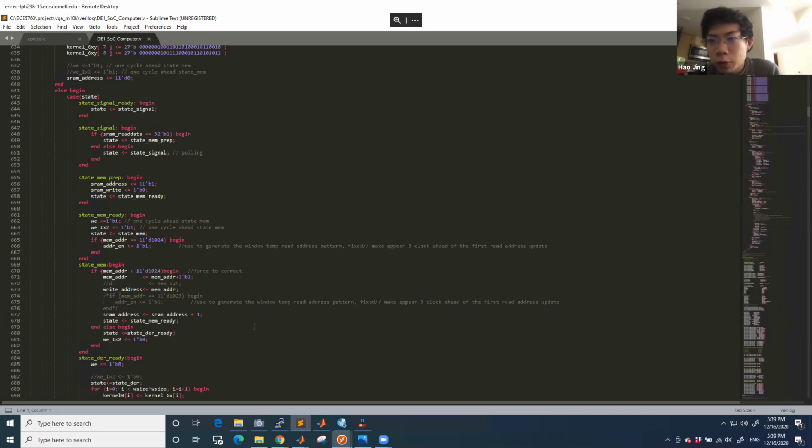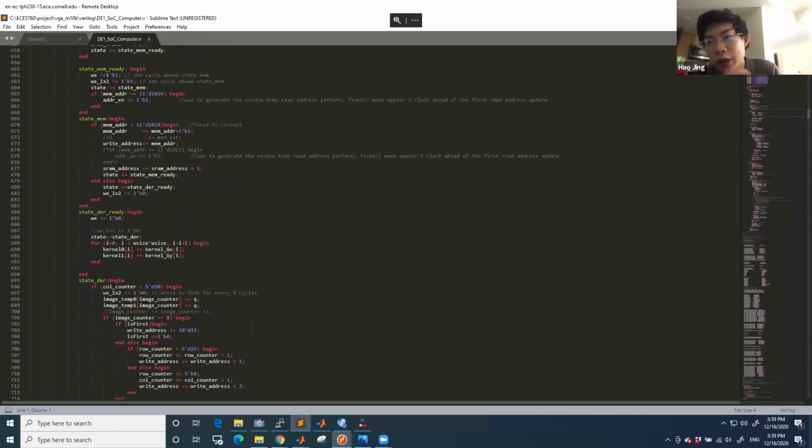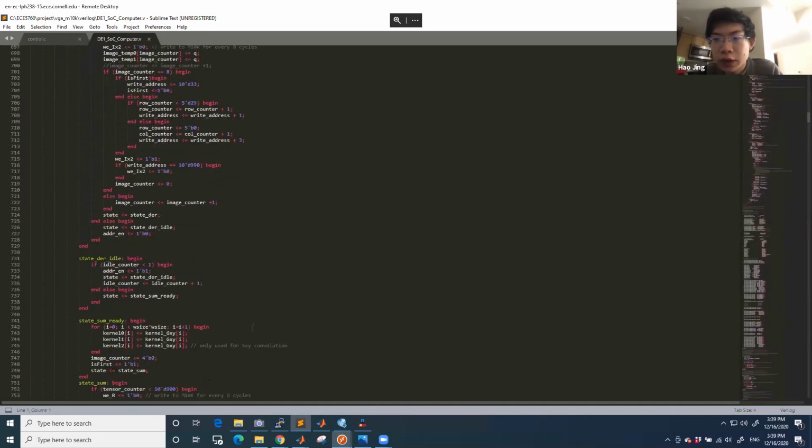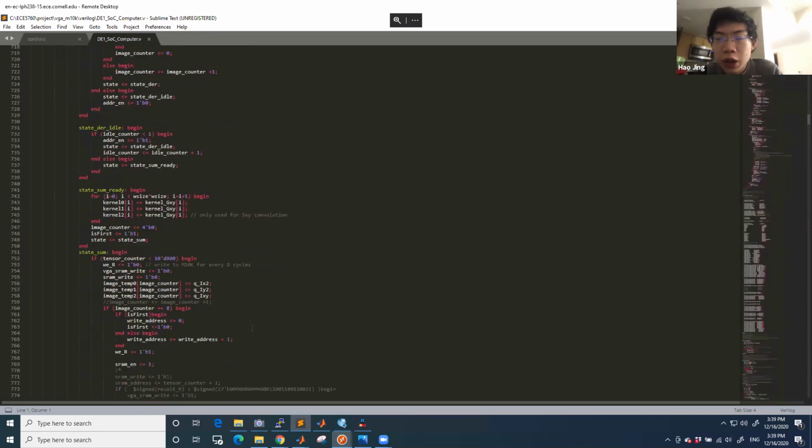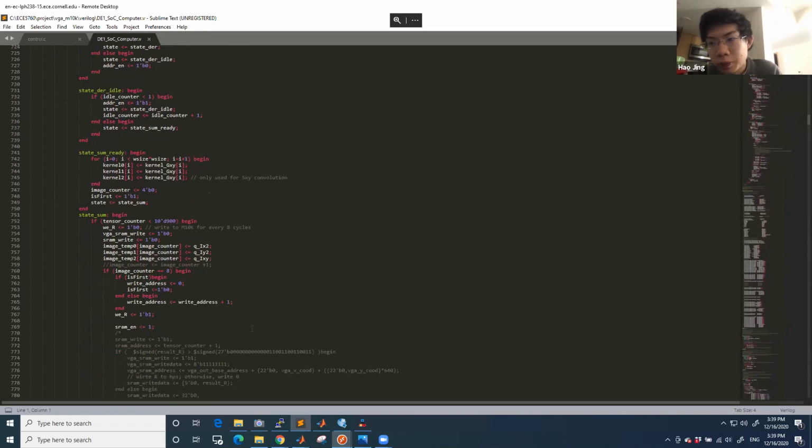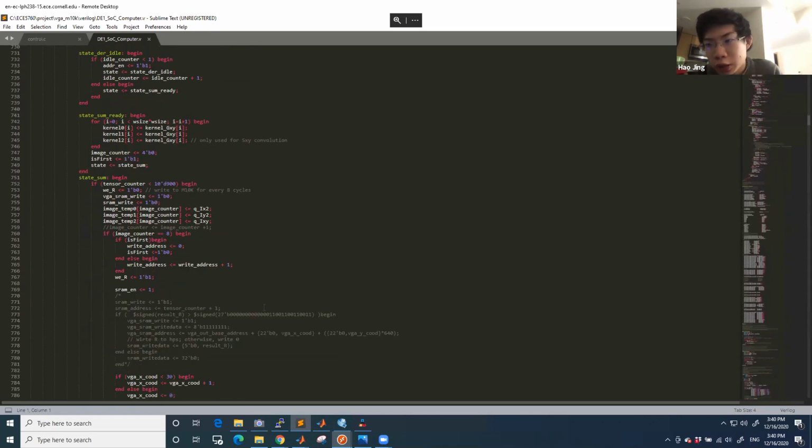These can be calculated in parallel on the FPGA hardware. Then we calculate our values one pixel at a time. We save all the R values into SRAM, then send them back to the HPS to do further processing, a recognition procedure that Sam talked about, which is KNN and a little bit of a voting algorithm.